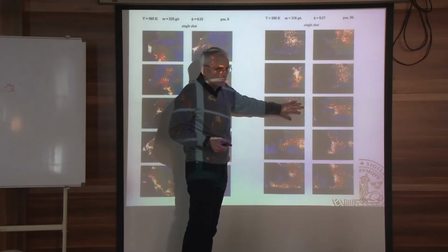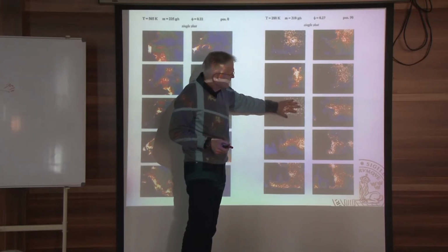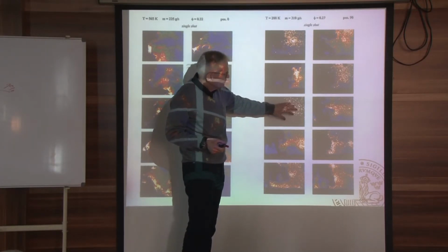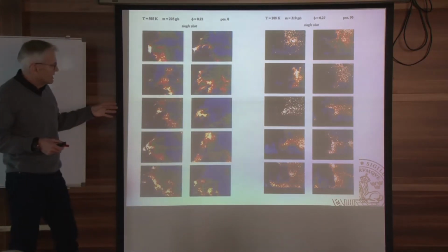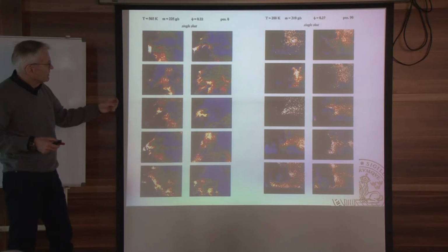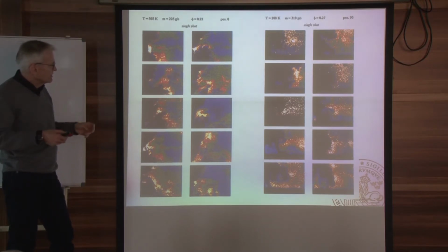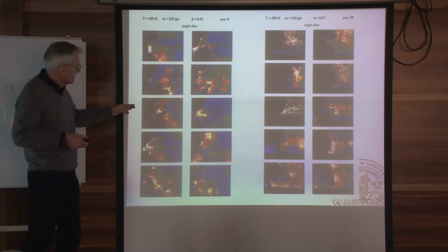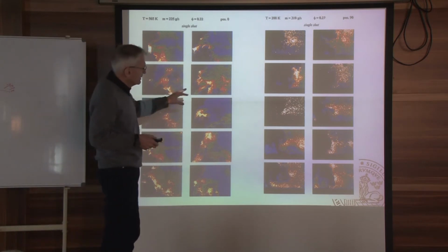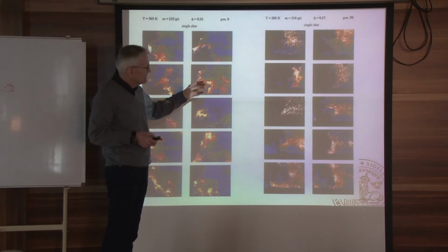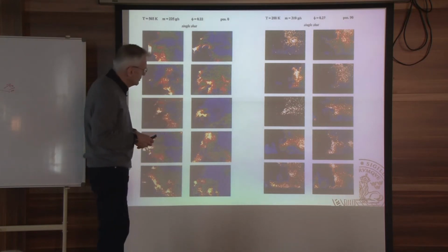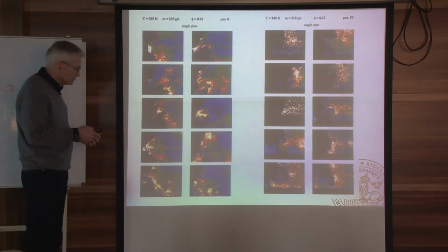This is OH emission from the flame. So we are in a mode of combustion, which is, I'm not quite sure where in the Borghi diagram we are, but the engineers and the scientists at Volvo Aero Corporation were extremely interested how this flame behaved in this very, very highly swirling flow.